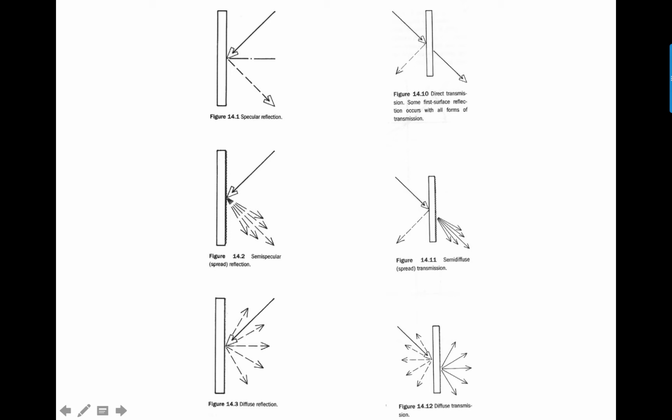same angle. Now, when you think of translucent materials, which is on the right, and this is anything from glass through to things like 3-form, then you'll get some direct transmission, but there usually is some kind of reflection. And again, you can have a surface that is completely glossy, somewhat transparent, and this might be akin to a fritted or sandblasted type of glass, to a fully fritted, very soft surface. And that diffuse transmission that you get through that surface can be really good if you want to spread out, say, a bright light source to make it a little less glary.